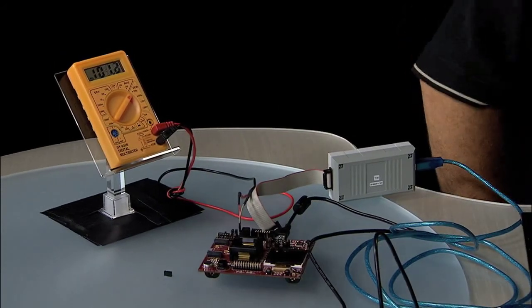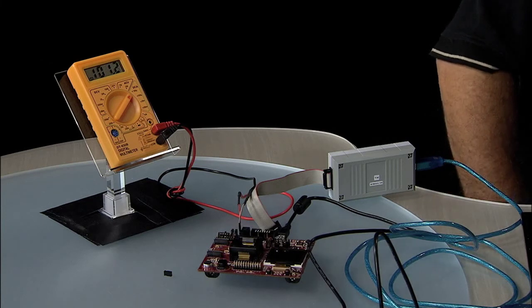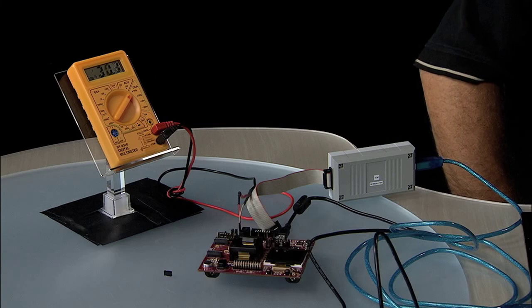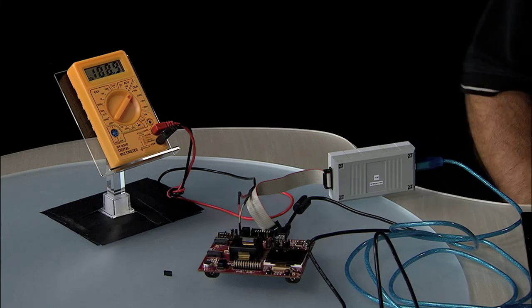So in this application, the CPU is not active either during the delay time or during the reference settling or the sampling. The CPU is allowed to wake up for a very short period of time to enter and exit the interrupt service routine and store the results. That's it.